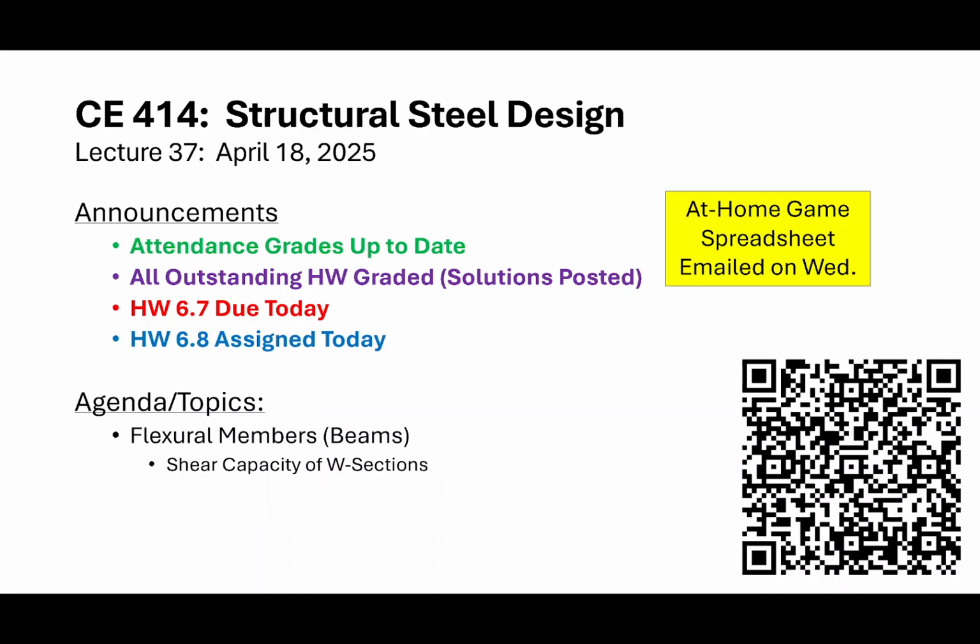A couple of examples: one of them is bridges, where you're customizing the size of the girder and tailoring the thickness of the plates, and so suddenly shear becomes a big deal. And there are a couple of applications in buildings, for example, transfer girders.